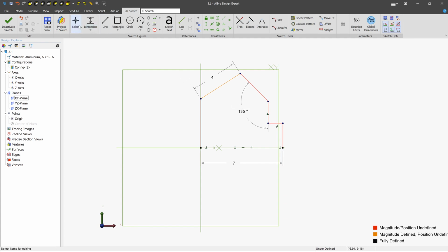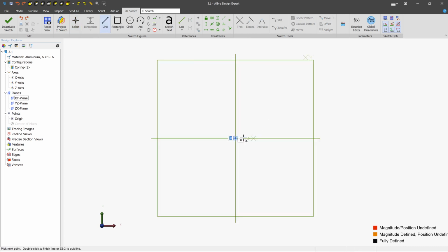If you'd like to delete particular lines, you can click the select tool, and you can select the line and just press the delete button. In this lesson, we've covered creating lines, stopping lines where you'd like them to be, continuing lines in a row, dimensioning lines in real time, creating dimensions like angles, dragging nodes around, inferencing of constraints during line creation like parallel, equal, or perpendicular, horizontal, or vertical. And we've talked about deleting lines by selecting them and pressing delete.